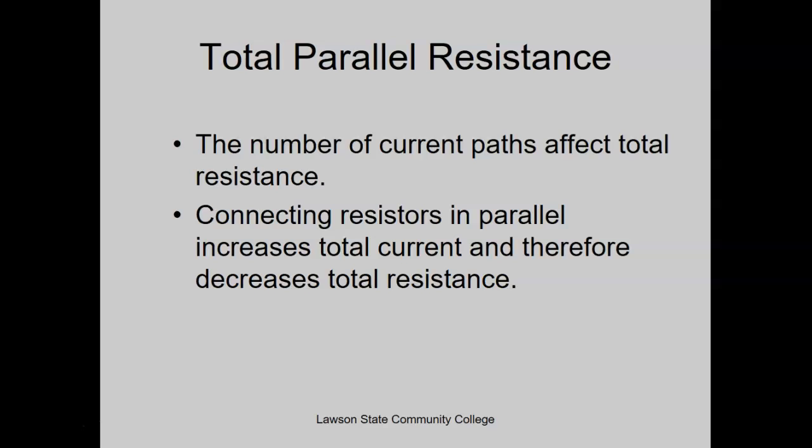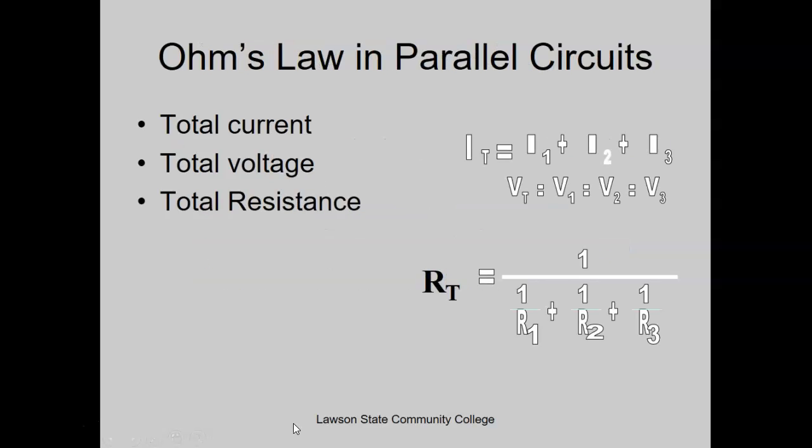This is why homeowners should not put in larger fuses or larger circuit breakers, because the wire can only handle so much. The wire is only rated for either 15 or 20 amps for most circuits in your house. That circuit breaker is rated for 15 or 20 amps according to the wire. If you overload that circuit and have it switched out for the wrong circuit breaker or the wrong fuse, the fuse and circuit breaker are supposed to give up first. If they can't, the wire will go next.